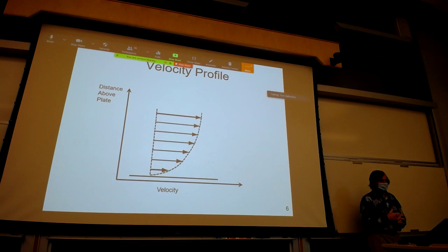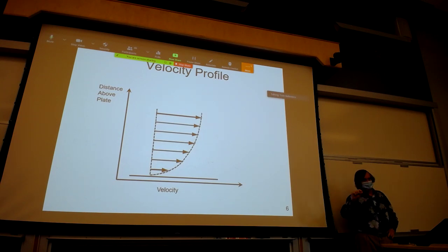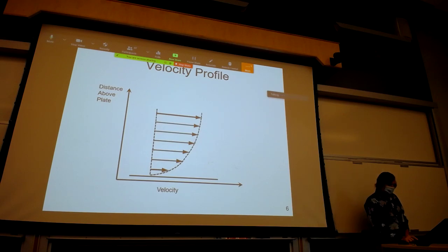By and large, with open channel flow, because of the roughness elements on the bed, typically you have turbulent, in some instances you could have transitional boundary layers. Laminar open channel flow is extremely rare. Places where you see it is on the thin veneer of water flowing down a cave wall, or when it rains really hard and you get a thin veneer of water flowing over a parking lot surface or a road surface, that can be laminar flow.